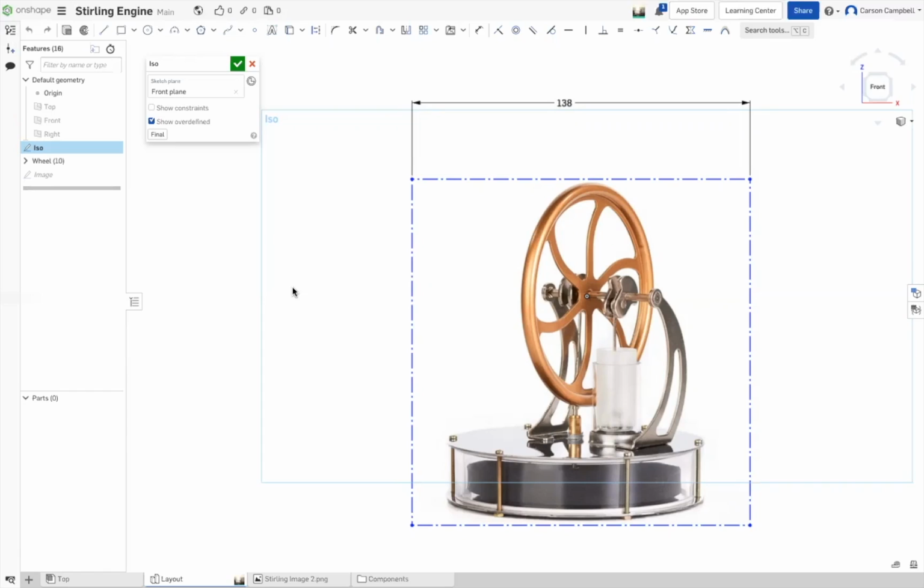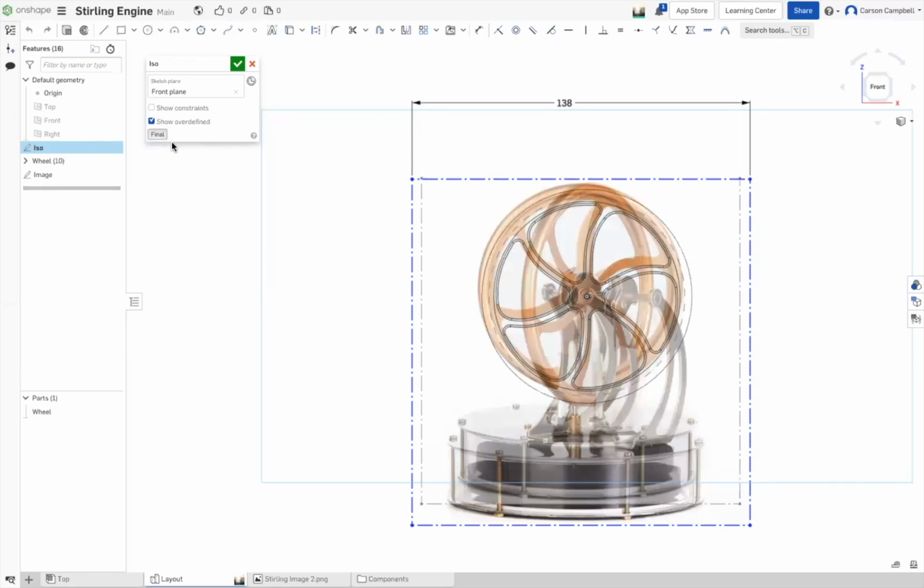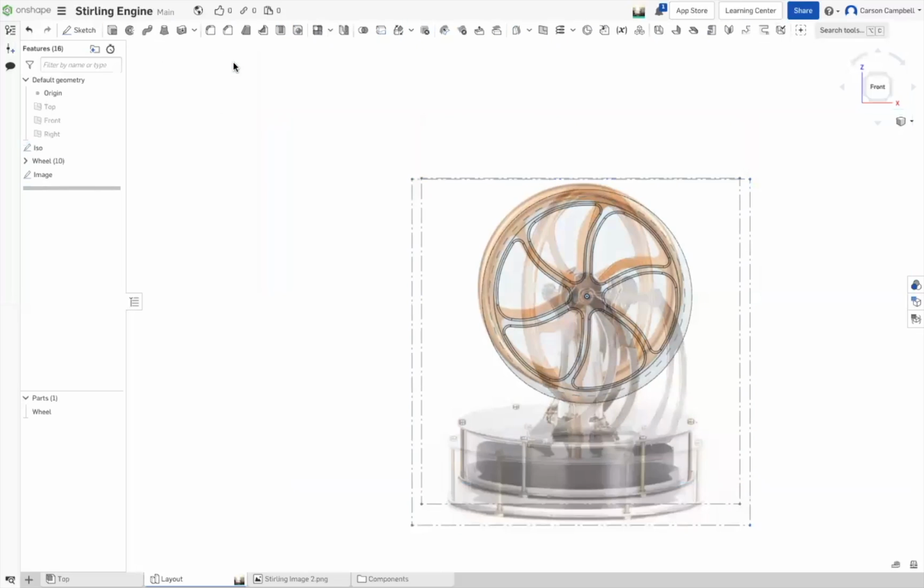Click on Final again. All that does is it goes through and puts the rest of the tree up there. So while you're editing a parent feature, you can see what all the children look like. Okay. Go ahead, say okay. It's just really cool. When I first saw that, I thought it was a waste of time, and now I use it all the time. Okay. All right, so with that being said,